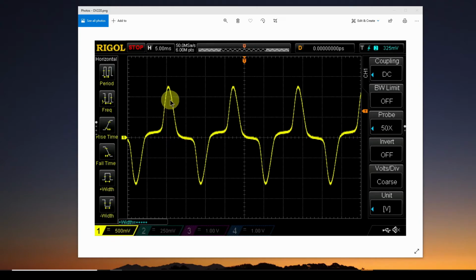So it's 0.5, 1, and a little bit, maybe 1 1/4. So you recall the peak current should be twice that because it's a 1/2 ohm resistor. So there should be a little over 2 amps peak flowing. And we saw that it was 1.1, something like that RMS, so that makes sense. So here's the actual waveform.